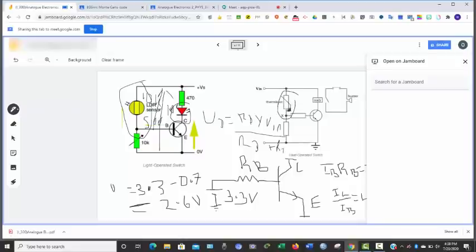This thermistor has to do with temperature. If it is positive temperature coefficient, PTC, it means if you are increasing the temperature, the resistance will be increasing. If it is NTC, negative temperature coefficient, if you are increasing the temperature, the resistance will be decreasing. But what we are interested in is that we want to know what will be my resistance, if it is PTC or NTC. And when you are able to get that, it will be a function of what will happen.